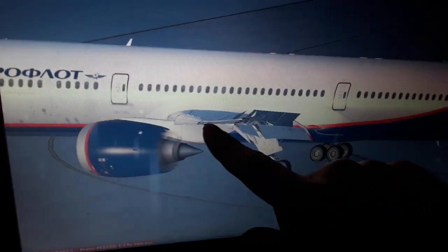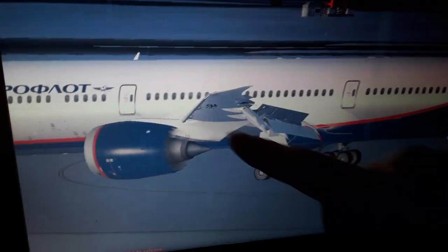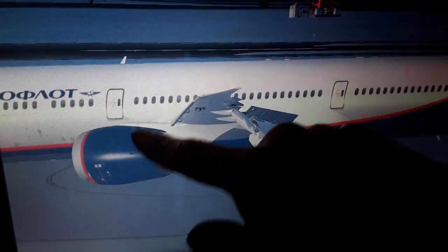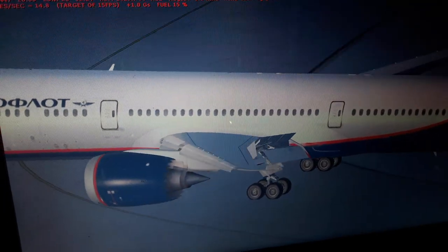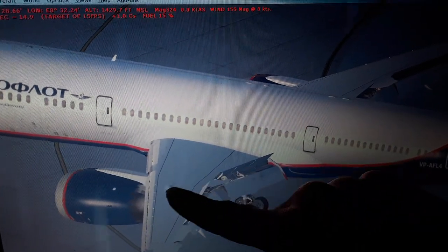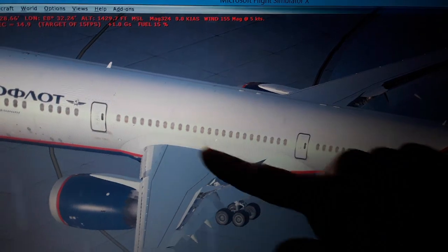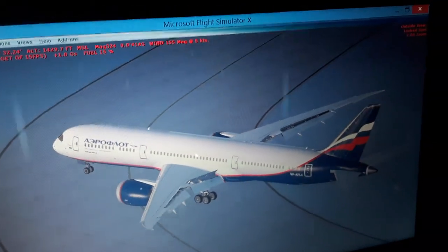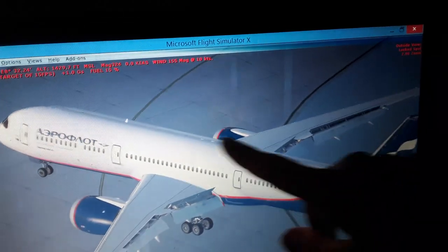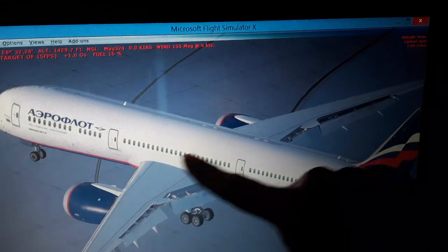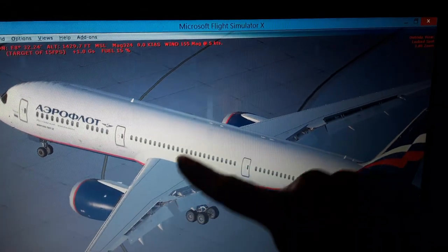So we have also the fuel flowing down from the suspension of the engine. Over here you can see we have the fuel lines, with the low and high pressure fuel valves open. We have also the fuel booster pumps over here, and the fuel tanks, left and right wing fuel tank, and the center tank over here. So we have also the wing and engine anti-ice hot air over here from the engines, also coming back from inside the aircraft from the manifold.